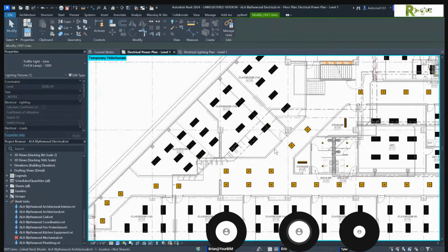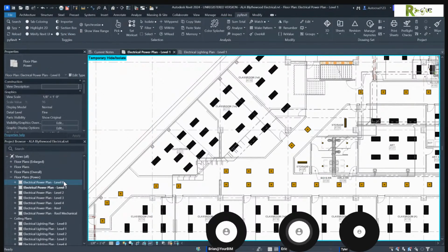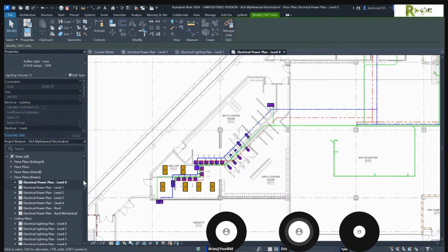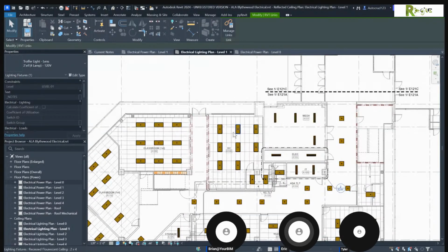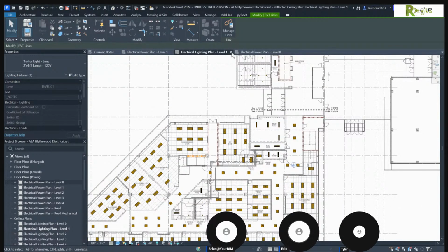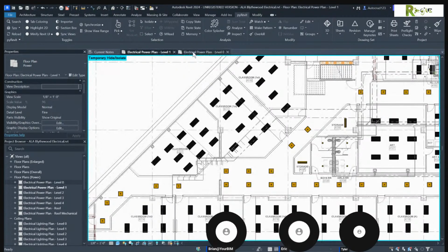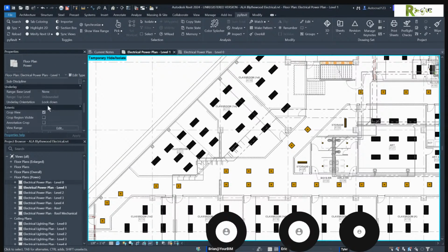All right, I got my view open. Just give me 1 second. Is that not the pipe for level 0? Because that's where the bathrooms are. Correct. It's the pipe in the ceiling for level 0. I think our cut plane needs to be looked at. That's what I'm trying to figure out right now. Go into level 1 and tell me what the view range is. It's down the ways just a little bit. I think you might have already passed it. Right there.